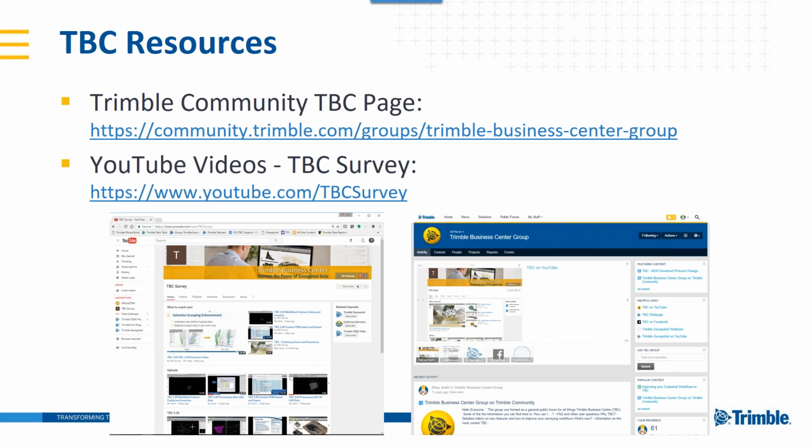We do have that capability, Abdul. What you would require is the GIS module. It's an add-on to TBC, and it will add on to any of the versions. What that allows you to do is connect to a geodatabase and map that feature information from the geodatabase into TBC, and we can automatically create feature code libraries based on that information. So it's very useful if that GIS workflow is what you need.